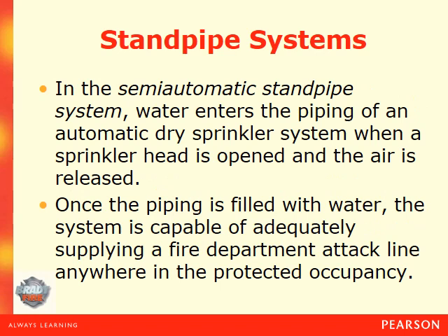In the semi-automatic standpipe system, water enters the piping of an automatic dry sprinkler system when a sprinkler head is open and the air is released. Once the piping is filled with water, the system is capable of adequately supplying a fire department attack line anywhere in the protected occupancy.